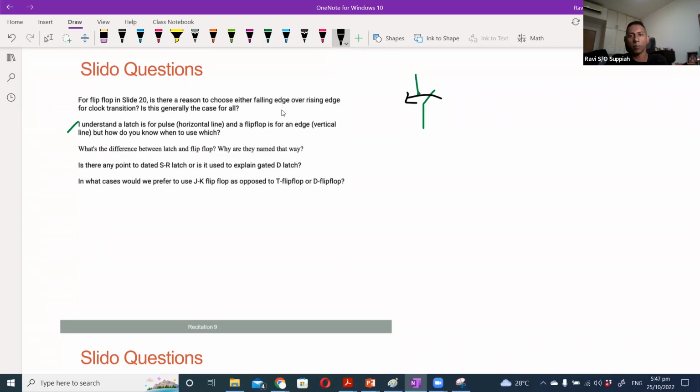Okay, so whenever I close the switch, it counts from 000 to 001 or 010. So if my aim is every time I press the switch, I want to increment by 1, then I can design a circuit such that I wait for the trigger. Whenever I press, I generate a positive or negative transition, then it keeps incrementing.